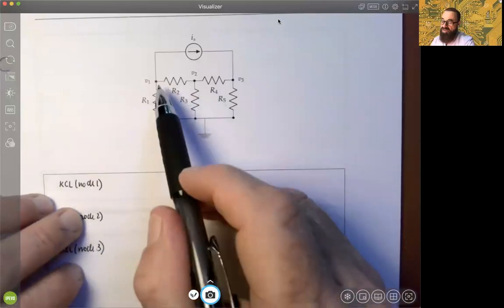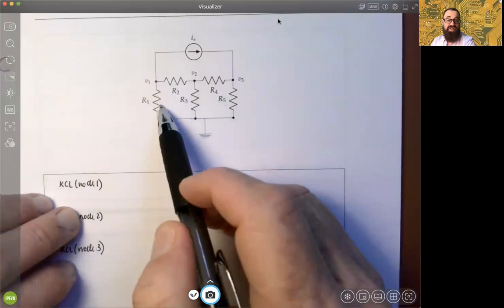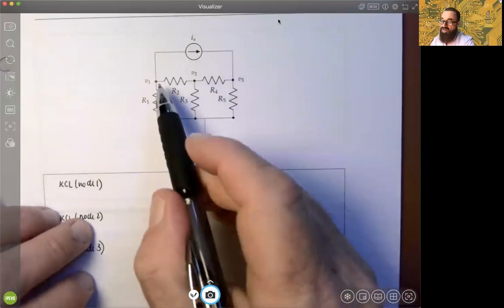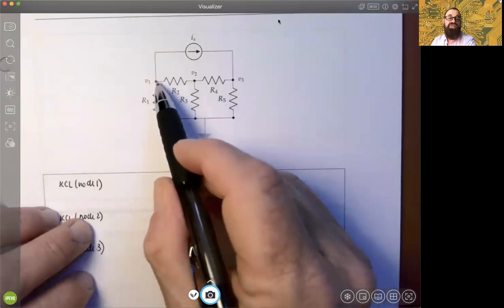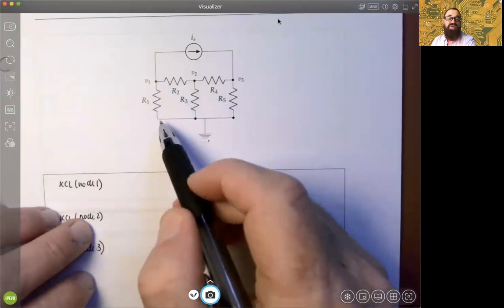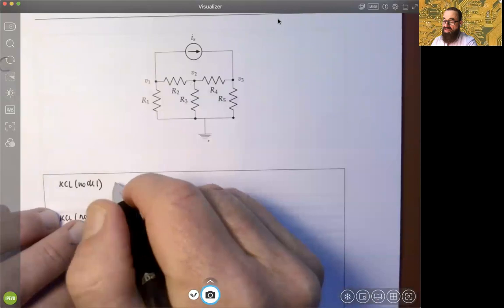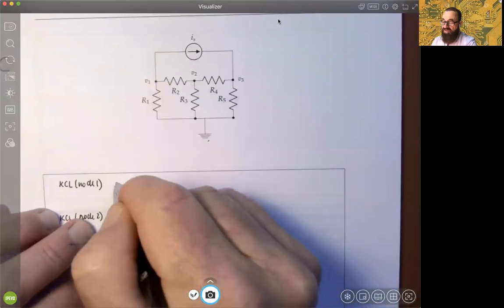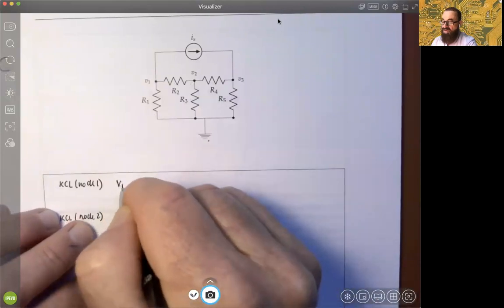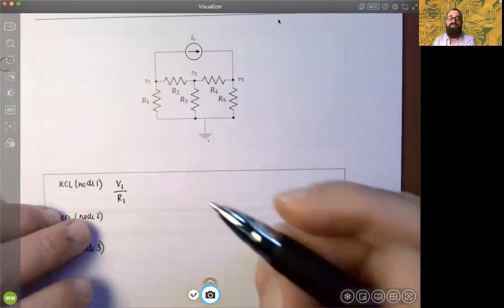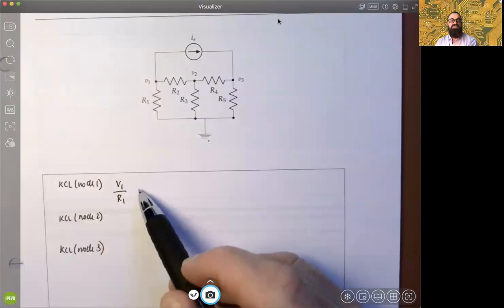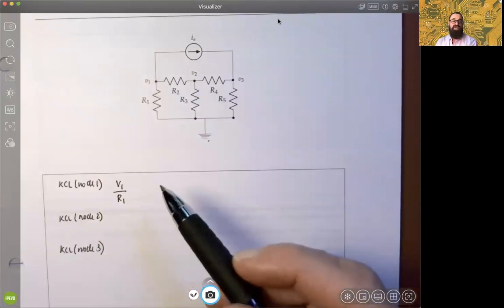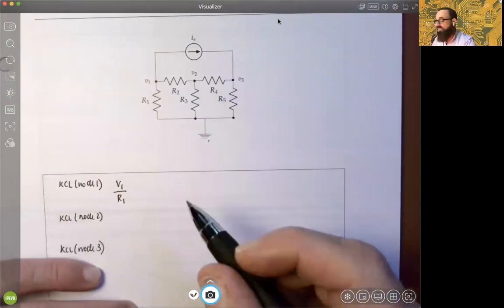The outgoing currents for voltage 1, you have 3, okay? Notice where the ground is. So one of the directions is down from V1 to the ground. So using Ohm's law, that voltage differential would be V1 minus 0 or V1 over R1, okay? So it's very simple. When you go to ground, you could say minus 0, but it's not necessary. Just say V1 over R1.